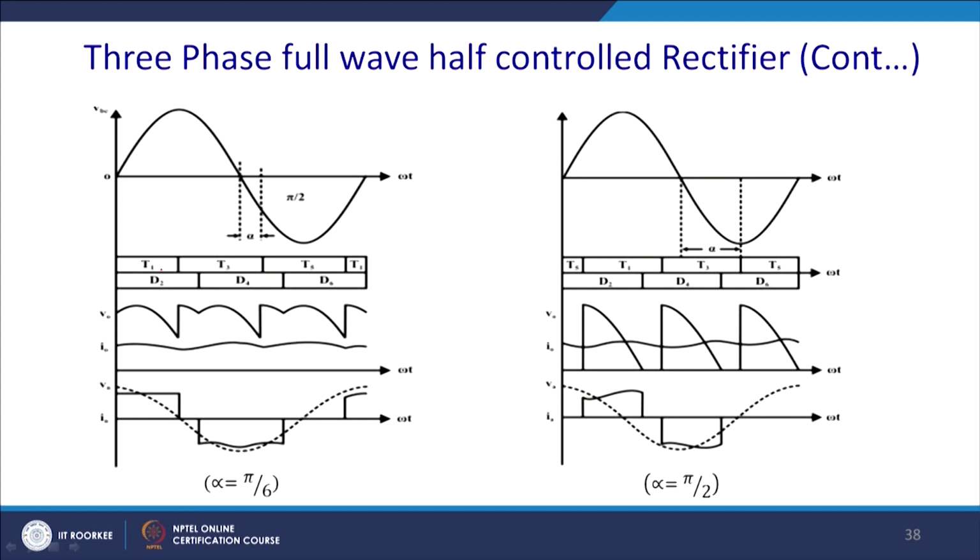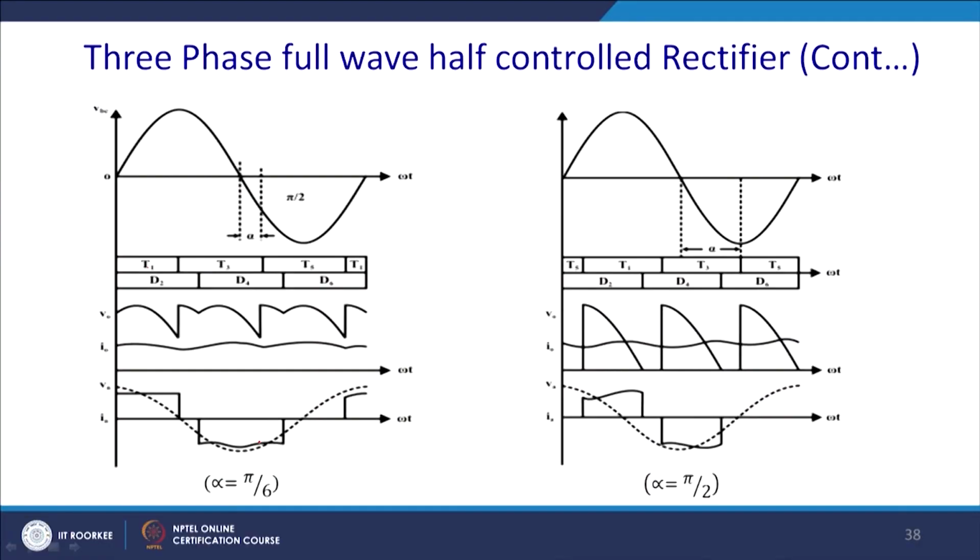T1 will be conducting for this period as shown here, and we can apply a delay to it, and since we can change the delay, the output voltage can be changed depending on the profile, assuming that the load current is almost constant. So, this will be the input current and this will be the fundamental. Same way, if you have this waveform with a large delay angle, then what will happen? You can see that this will be the pattern.